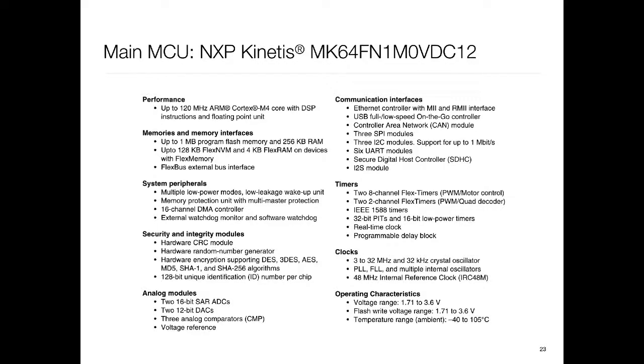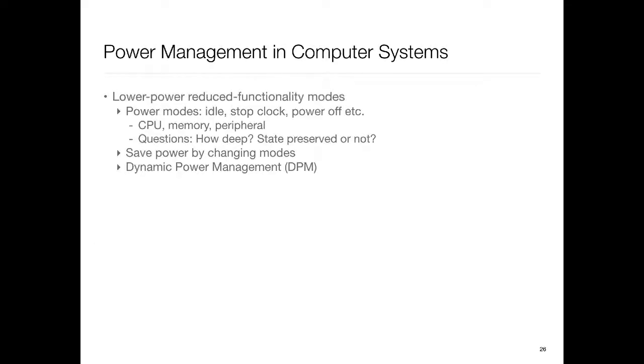Yeah, this thing doesn't provide it, but this particular processor, for example, does have many states, and there would be some way of accessing them. Now, operating systems abstract this away. For example, Mbed provides some APIs for you to put things into a shutdown mode. A very common way is to go into this mode and wait for an interrupt. The idea is the system goes into a low power mode until something happens, like a packet arrives or a user clicks a button.